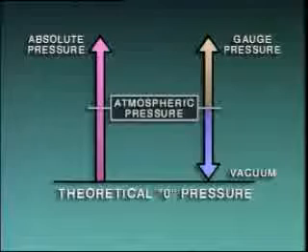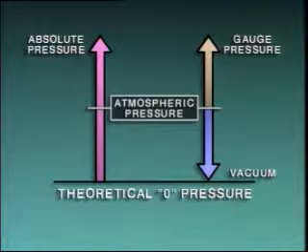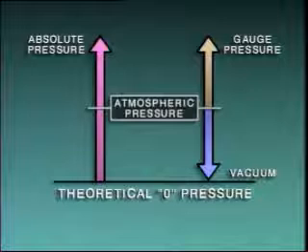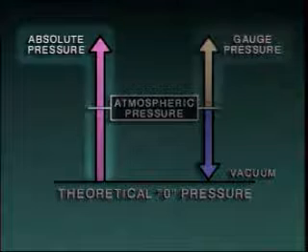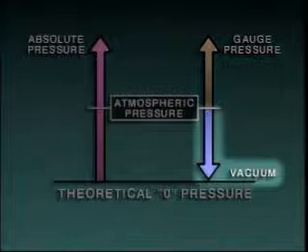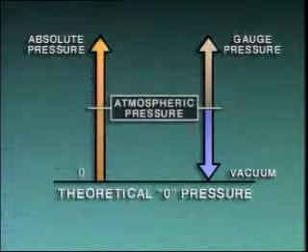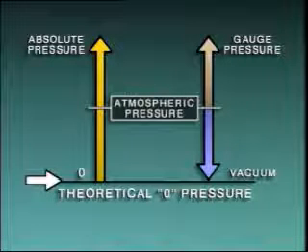The pressure exerted by a contained gas is a result of collisions between the molecules of the gas and the walls of the container. The way that atmospheric pressure is taken into account depends on the scale used to measure the pressure. 3 scales commonly used for pressure measurements are the absolute pressure scale, the gauge pressure scale, and the vacuum scale. The absolute scale begins at theoretical zero pressure, a condition of no pressure and a total absence of